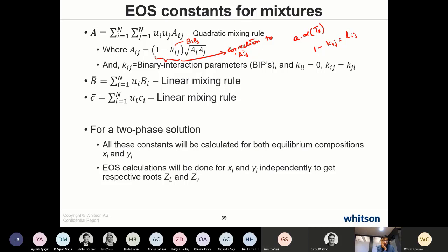You mean which parameter to change, like volume shift or the binary interaction parameter? Yeah, because when you have an uncertainty in vapor pressure, that means that you can also move the vapor pressure a bit. And that will change the density. So how do you know whether to correct on density or to correct on vapor pressure? How to tell on a C7 plus component.